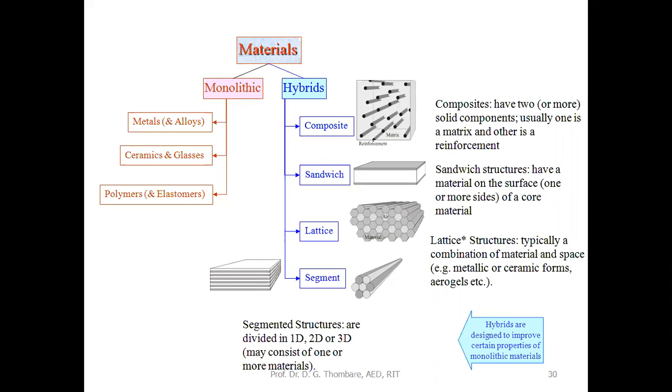Here, composite means you have two or more materials together, arranged in such a fashion that they make a matrix that provides desirable strength. Aircraft parts are mainly made of composite materials, because they must be lightweight and at the same time have very high strength.